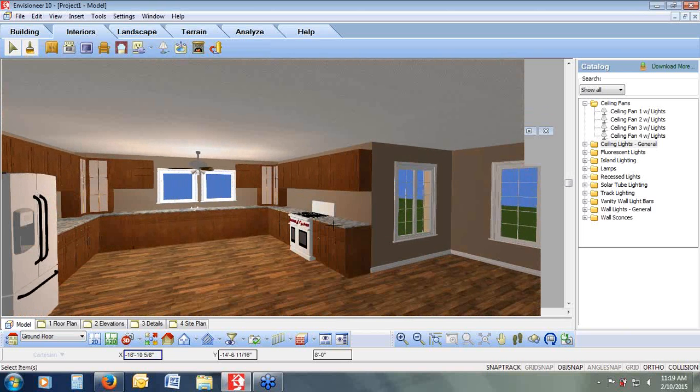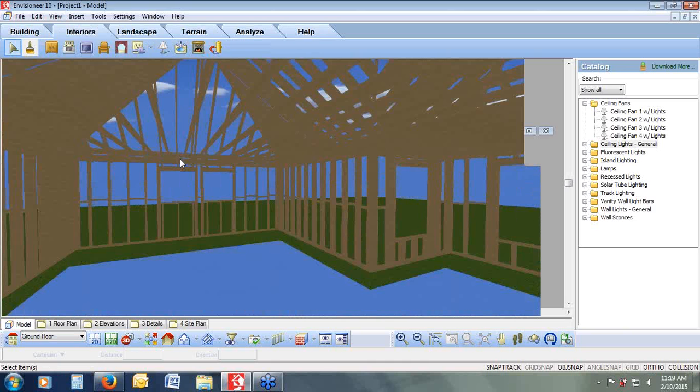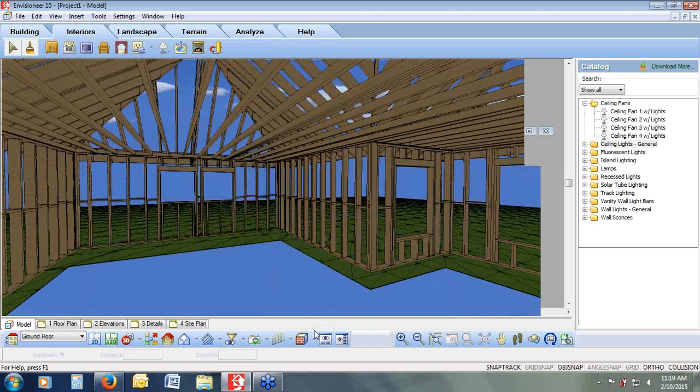While you're taking them on the virtual tour, what the software is doing in the background is also thinking about the structure behind it. So if I display the framing, it'll show me all of the wall framing and the roof framing and ceiling framing if I've specified it in my design, and I'm going to put that into a rendered outline type of view. You have the opportunity to tell it exactly how you want to frame each wall. Do you want blocking halfway up the wall or not? Do you want a double top plate, single bottom plate? What's the size of the headers?